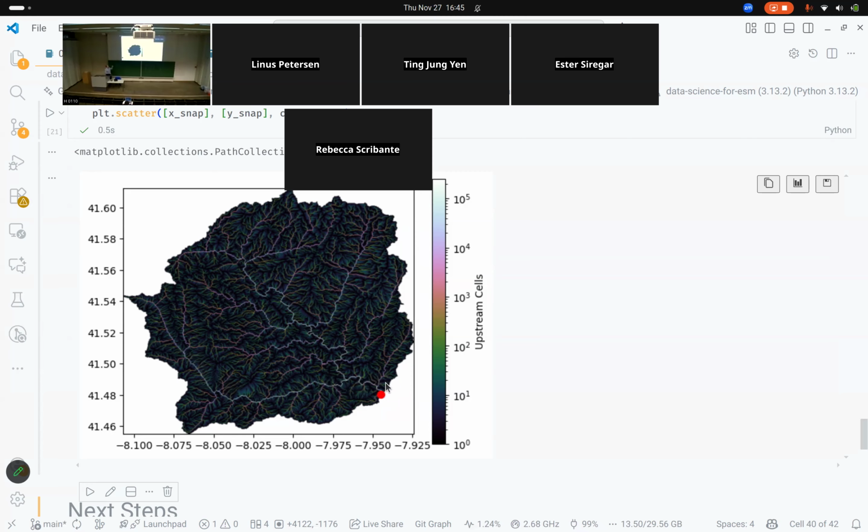And we can now do things like calculating the general area of the catchment area. And if we combine it, for example, with this ERA5 reanalysis dataset, we can look at, well, this catchment area, in which raster cells of the weather data does it lie? What are the statistics about the rainfall, the evaporation, and so on? And then calculate basically daily water flows at this point, which we can then later use for calculating the power production potential of a potential run-of-river plant with a dam at that red point location.